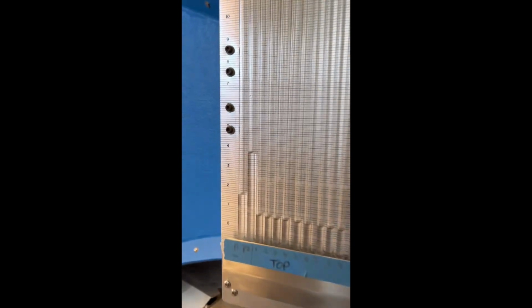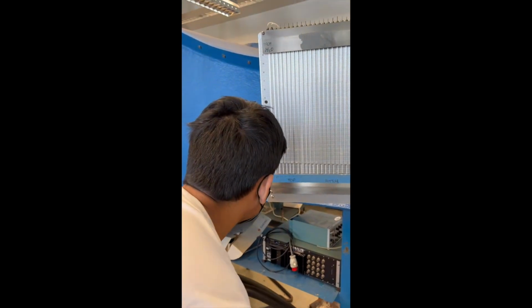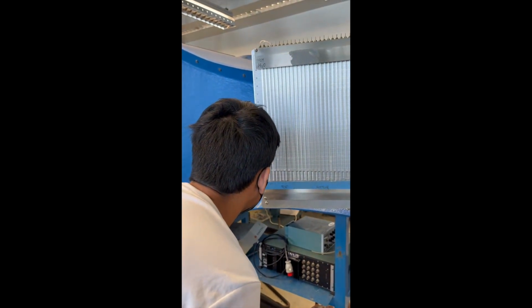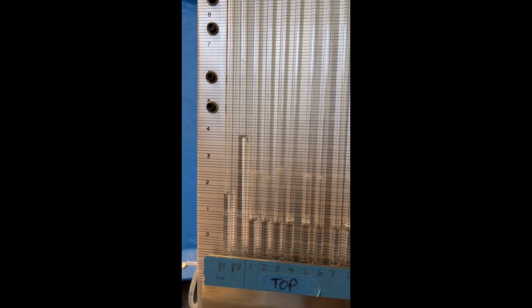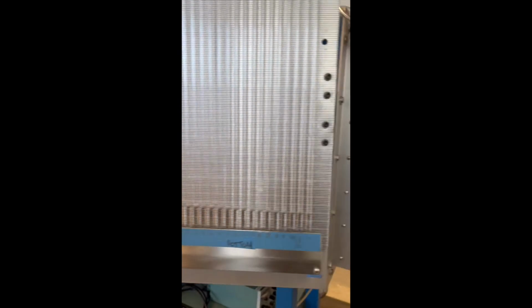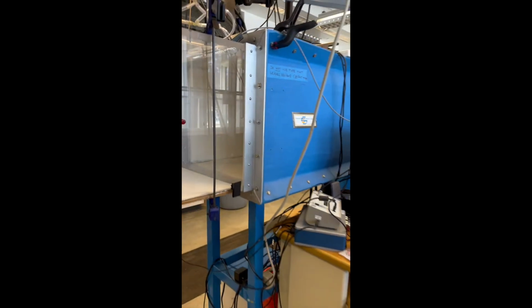This allowed me to get the force and water level at all three speeds in my data tables. From there, I would reset speed to 0 and then wait for 1 more minute. Then I would stop the wind tunnel and go back to the force load cell and record the force again. This allowed me to record force drift and gave me a quantification of uncertainty for my data analysis. From there, I would stop the run and rename the data file, and then repeat these steps for the other nozzles.